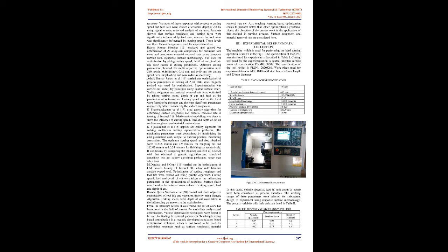Anil Gupta et al. [8] carried out multi-output optimization of surface roughness, cutting force, tool life and power consumption using the Taguchi method with logical fuzzy reasoning. Machining parameters considered for the CNC turning of AISI P20 tool steel were cutting speed, depth of cut, feed, nose radius, and cutting environment.